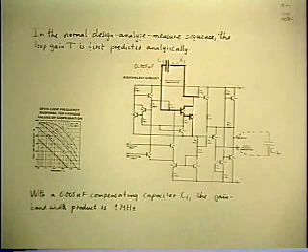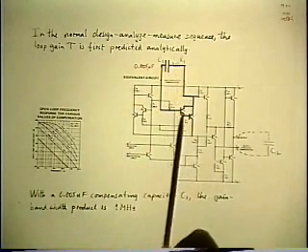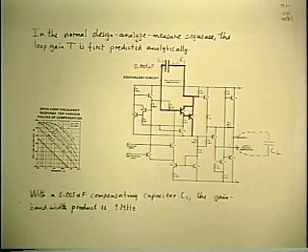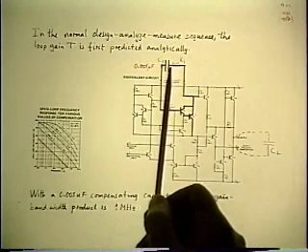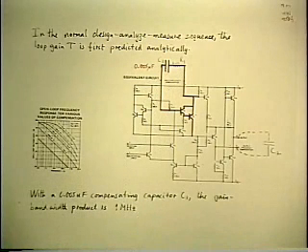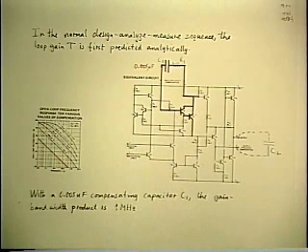One of the occasions where it could come down is where the collector base capacitance is not the 5 picofarads that's inherent in the transistor, but you may have purposely put a much bigger one outside. That's exactly what I did. I put 100,000 picofarads outside. And that's what brought the right half plane 0 down all the way to 12 kilohertz.